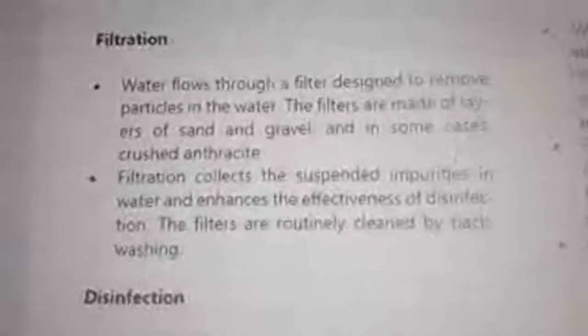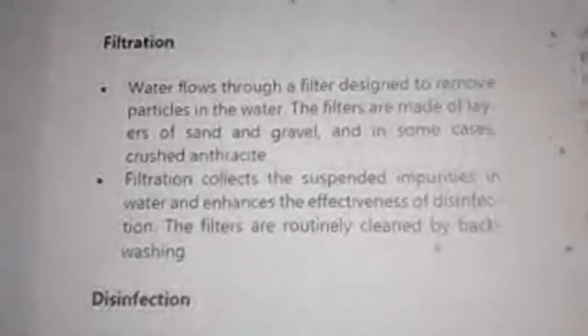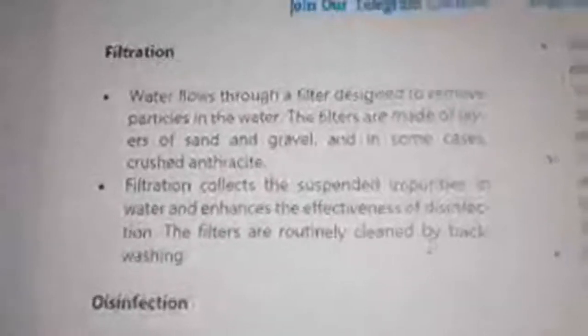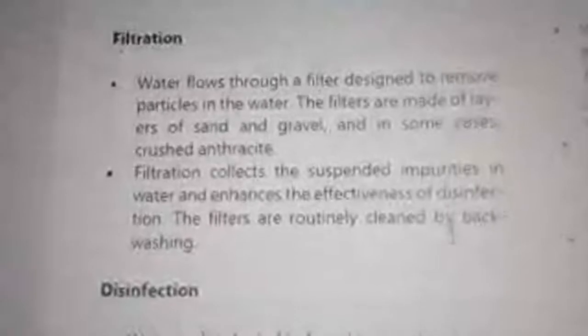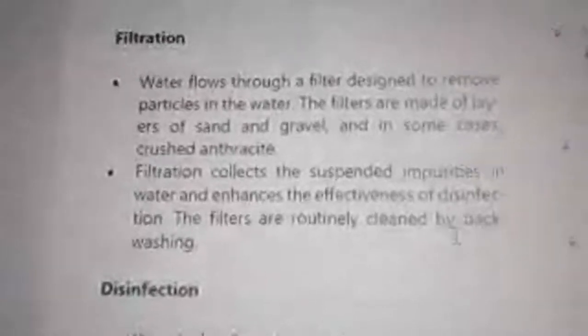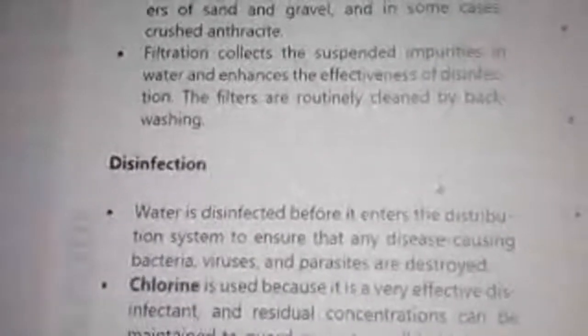Filtration. Water flows through a filter designed to remove particles in the water. The filters are made of layers of sand and gravel, and in some cases, crushed anthracite. Filtration collects the suspended impurities in water and enhances the effectiveness of disinfection. The filters are routinely cleaned by backwashing.